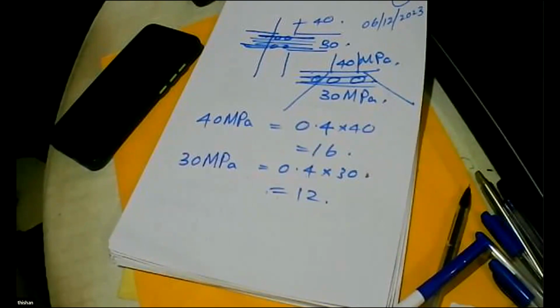But I think the design engineer probably asked for 40 megapascal, which is not a good thing. And anyway, in Sri Lanka, pile rafts are not necessary. Pile rafts cannot work in Sri Lanka because Sri Lanka has bedrock. Pile rafts work only with friction piles, not with end bearing piles, so it's a wrong concept.